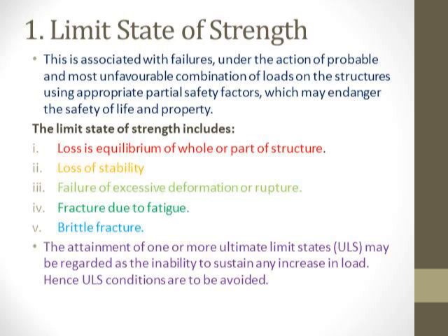The attainment of one or more limit states may be regarded as the inability to sustain an increase in the load. Hence ultimate limit state conditions are to be avoided. These ultimate limit states are those catastrophic states which require a larger reliability in order to reduce the probability of their occurrence to a very low level.